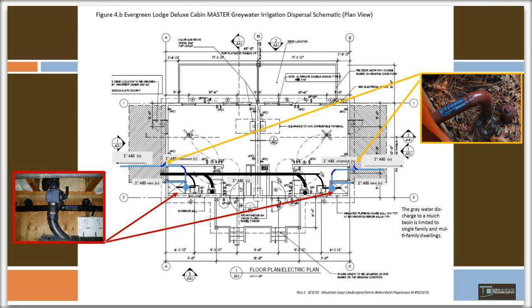These cabins are duplex cabins, and here's a layout where there's 2 cabins, essentially a duplex. We very simplistically, just like you would in a residence, use a diverter valve underneath the cabin, and we put it out to the surrounding landscape. So there's no pumping. And if you're not familiar with branch drain systems, please look them up on the Greywater Action webinar.